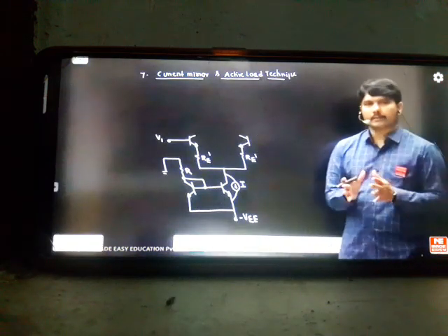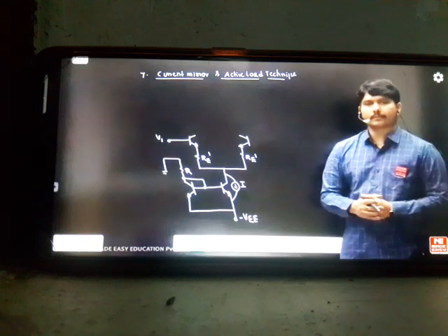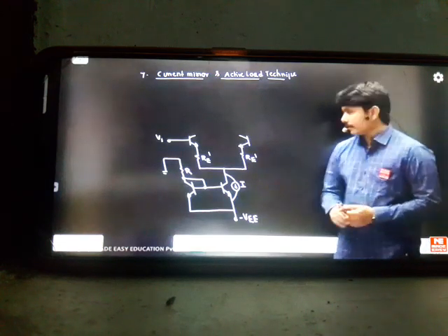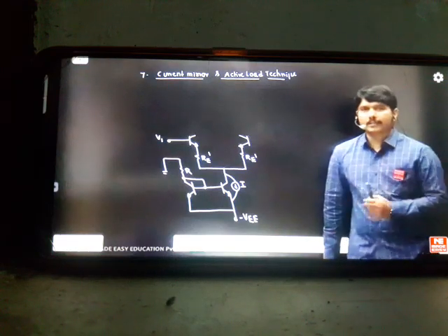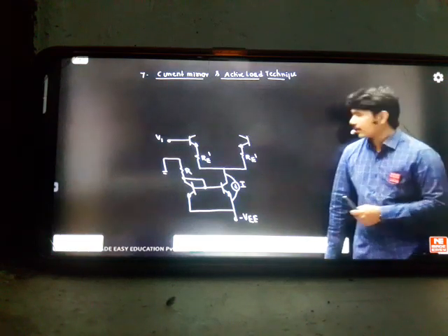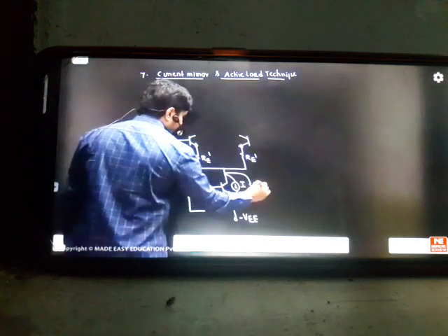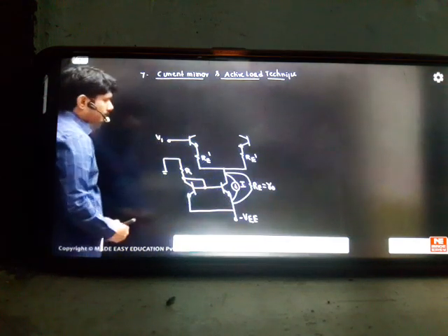In place of the capital RE resistance, we want to convert the resistor into a current source, because in our networks course we understood that an ideal current source gives infinite impedance. We need infinite impedance there to reject the common mode signals well. So for common mode rejection, we need a constant DC current, and in the current source, AC current should not enter that path. Therefore, with a practical resistance, capital RE will become R0.